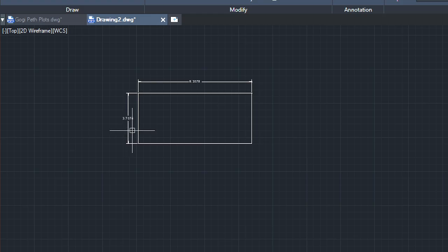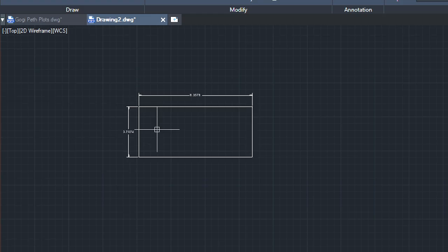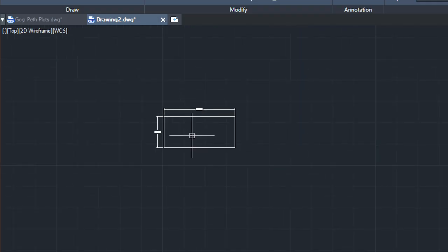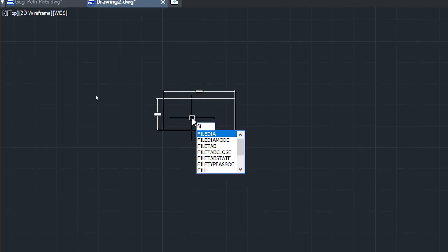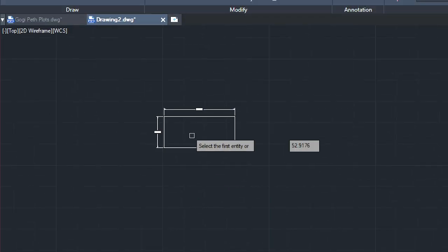What I'm doing here is I have used the rectangle tool and created the rectangle. I have used the dimension tools, so I showed the dimension here in the model space only. So all together we are using the drawing tools, and modification tools also, to modify the drawings.